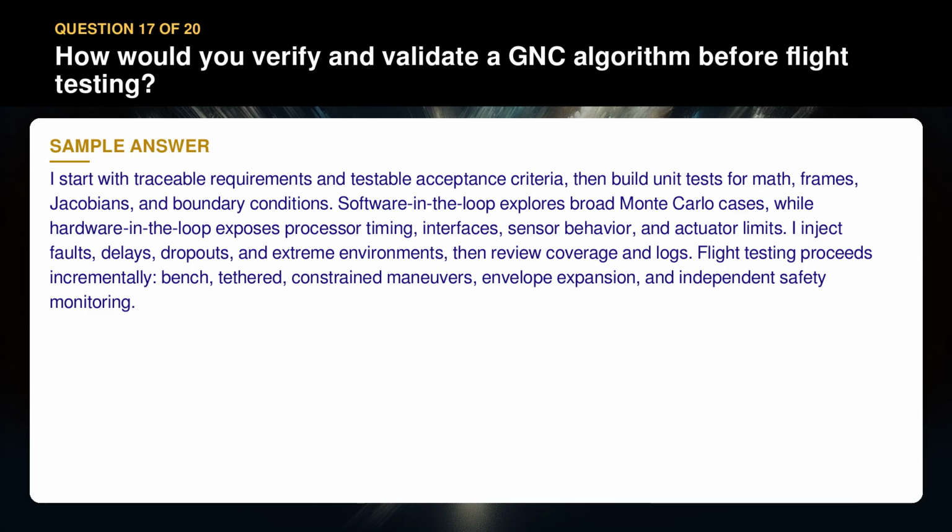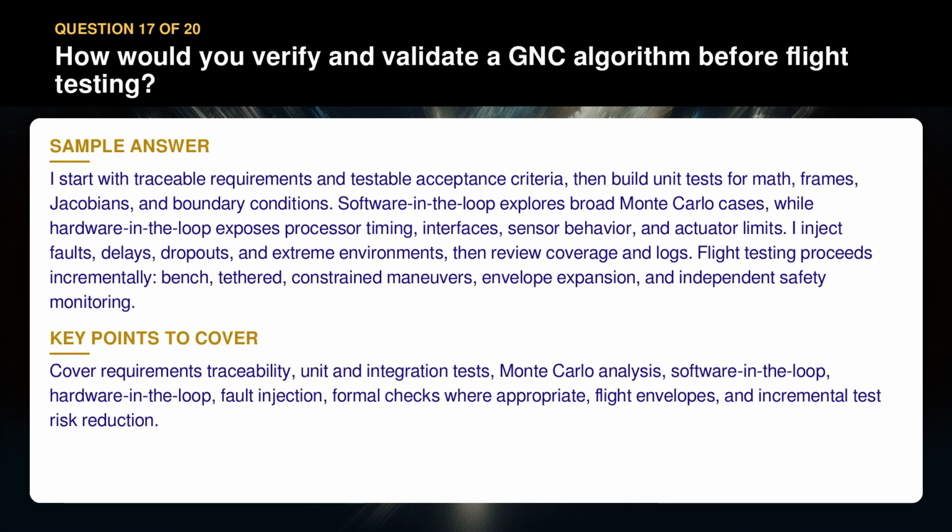Flight testing proceeds incrementally: bench, tethered, constrained maneuvers, envelope expansion, and independent safety monitoring. Cover requirements traceability, unit and integration tests, Monte Carlo analysis, software in the loop, hardware in the loop, fault injection, formal checks where appropriate, flight envelopes, and incremental test risk reduction.